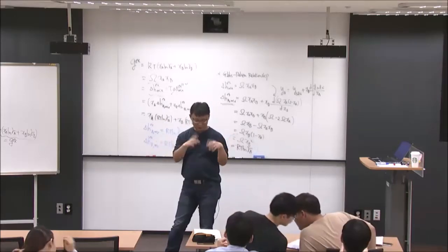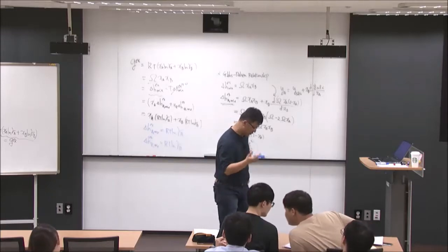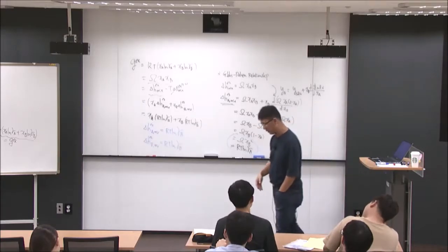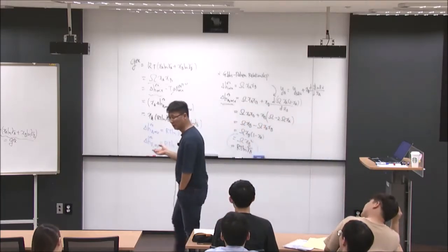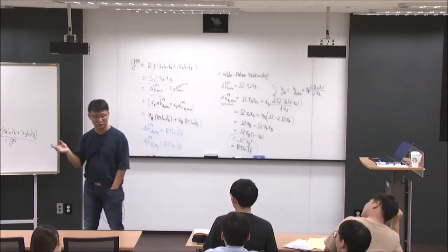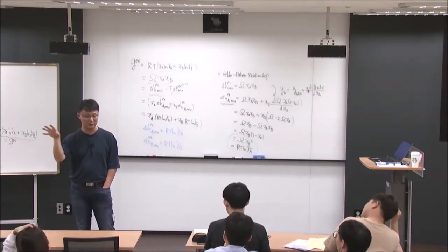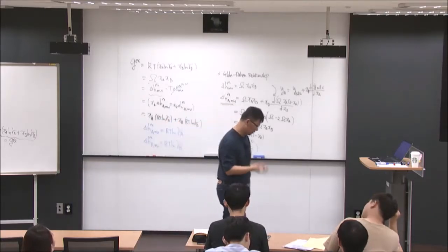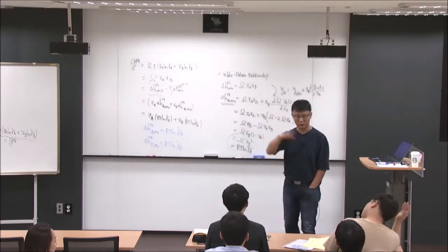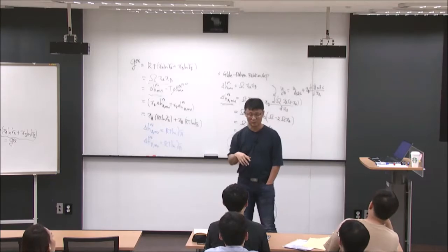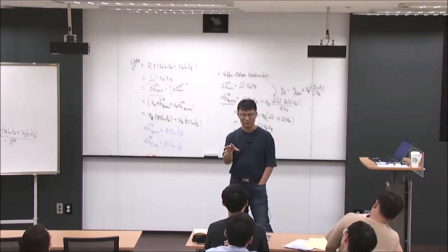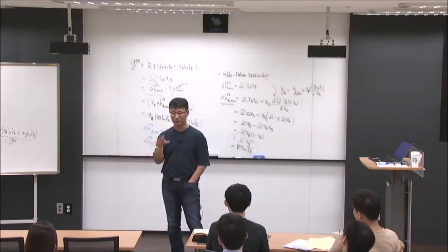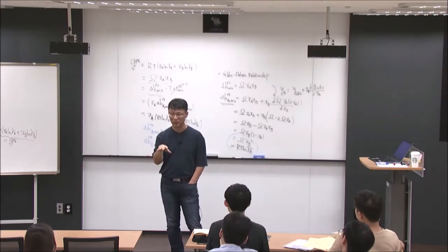And then we learned basically all these thermodynamic laws, and then we derived the equation. Even though we had the first law, second law, and third law of thermodynamics, that is not enough to apply in materials thermodynamics. So we derived a new equation called the Gibbs relation, Gibbs energy equation, yeah. And Gibbs energy was H minus TS. The reason why we derive the Gibbs energy is we don't want to take care of all the surroundings of the system, because we are just focusing on our own system, and in order to tell whether our system is in equilibrium state or not, we have to find some new relationship beyond the second law of thermodynamics.